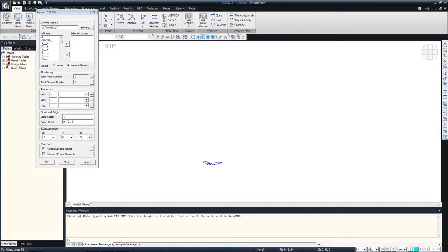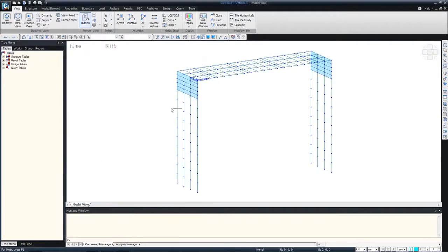So to change the unit system, there is a very quick way of doing it. There is an option in the status bar. You can just switch between different units, say millimeters, and you can select the layers which you want. So say I just select everything. Here assign some default materials or sections, whatever it is. Click OK, and you've got an integral bridge.